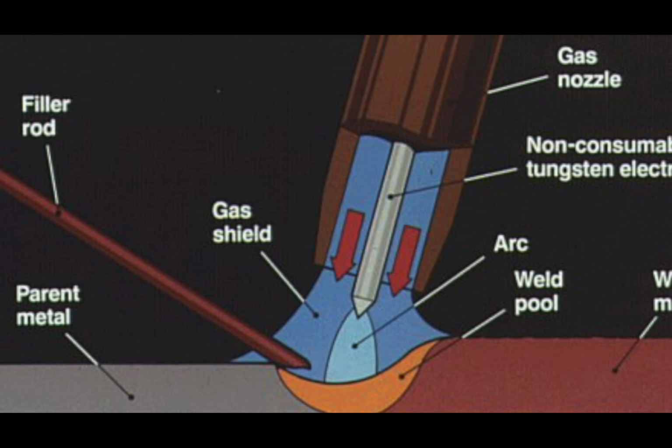Joining attaches two parts using various methods such as fasteners, adhesives, and welding. Welding is usually used to join metals or thermoplastics. The material being joined is melted and a filler material is added to create a pool of molten material that cures into a solid joint.